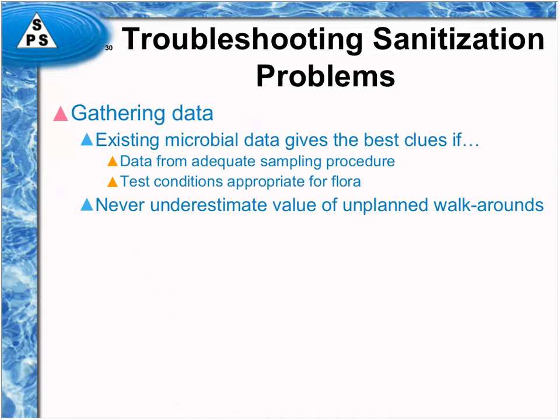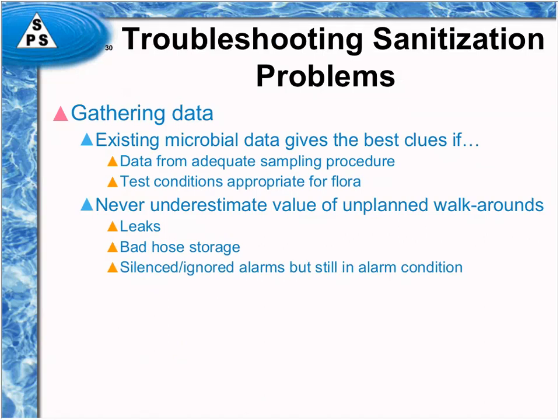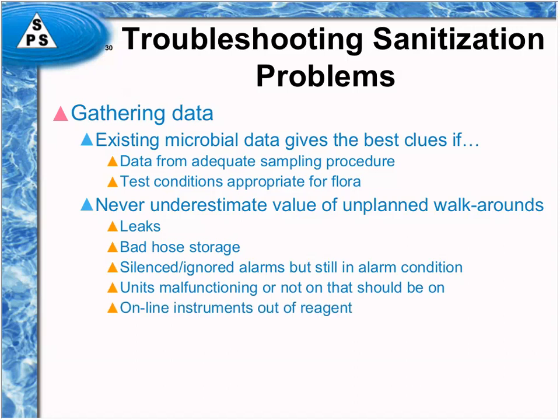Also, never underestimate the value of unplanned walkarounds. Oh my gosh, how valuable they are. You will be able to see leaks that you didn't know exist. You will see bad hose storage. You will see silenced or ignored alarms that are still in an alarm condition. You may see units that are malfunctioning or not even turned on. You'll see online instruments that are out of reagents and not functioning. And the alarms have long since been silenced.